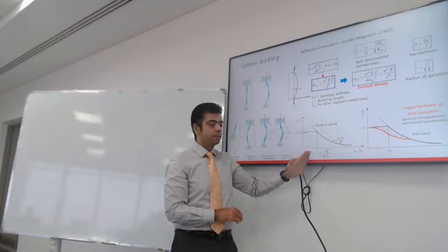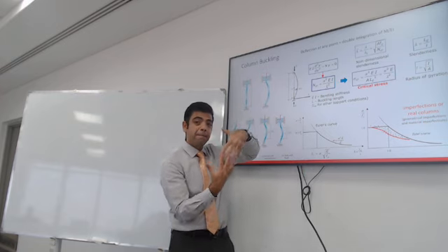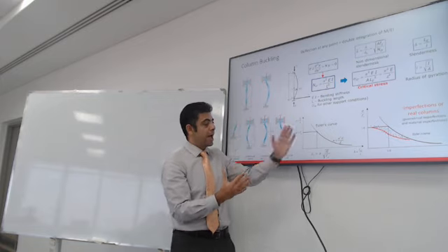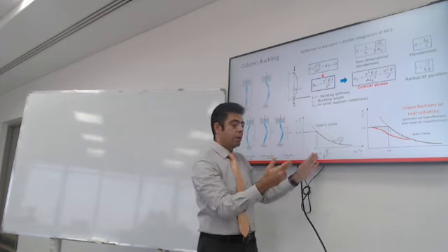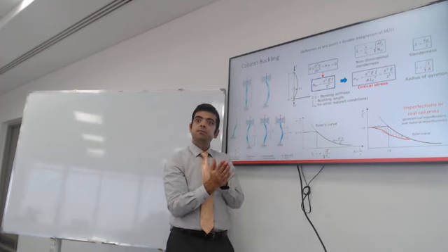Anything less than lambda 1, this is failure under compressive yield. That's the maximum stress you can achieve in the column. Anything right of lambda 1, buckling will have an effect. Does that make sense?